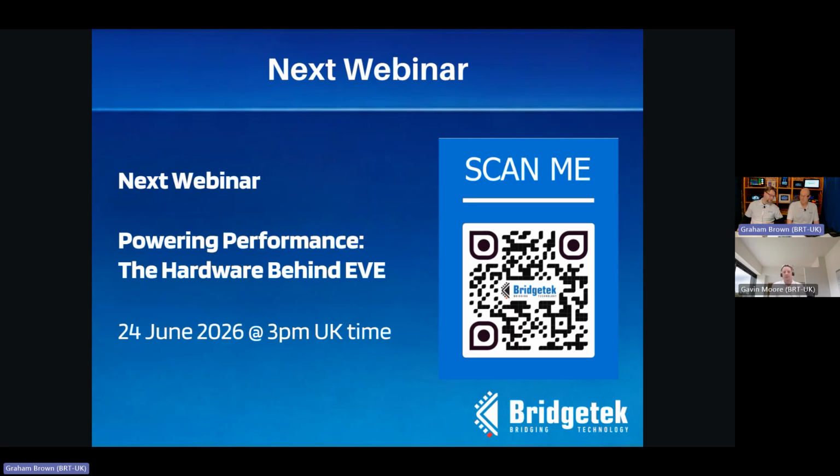We were using the DP0701-01A module, and this is a TFT display module that we currently sell, and you can purchase to put into your application if you so desire. This is an 800 by 480 WVGA resolution TFT display module. It has a capacitive touch controller which supports up to 5-point multi-touch and utilizes a 50-pin RGB FPC cable to drive the display.